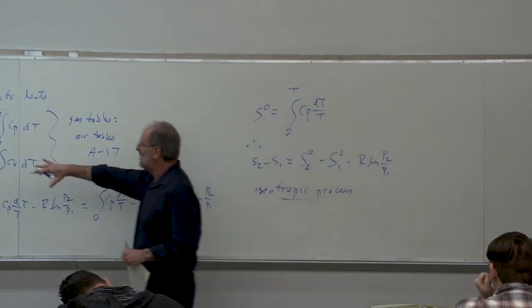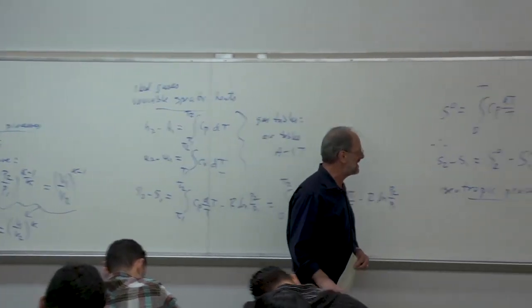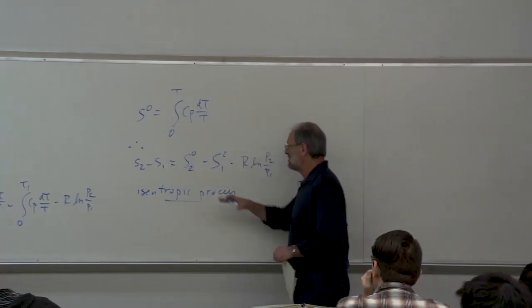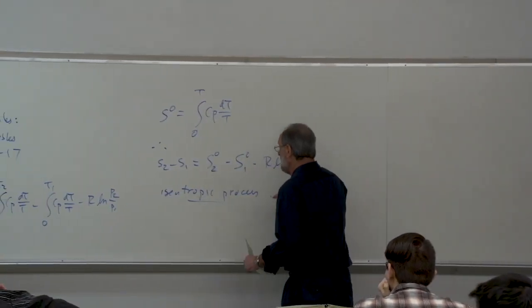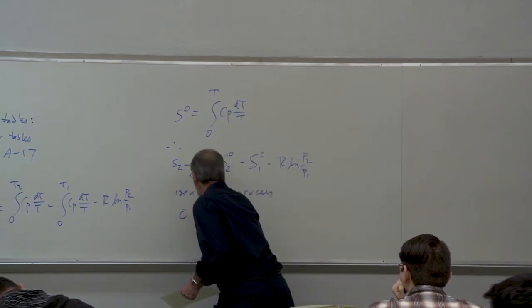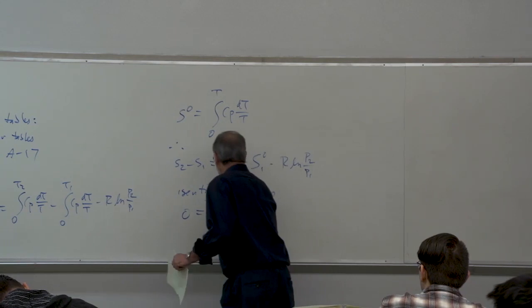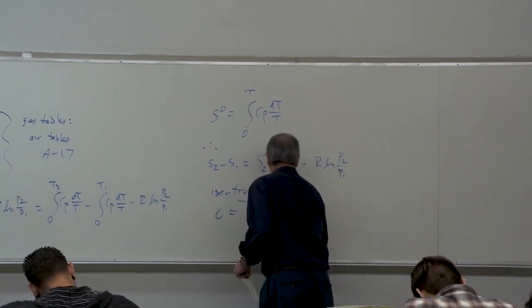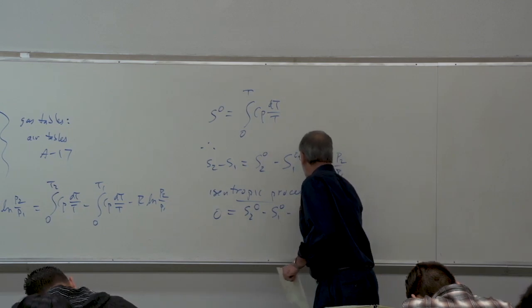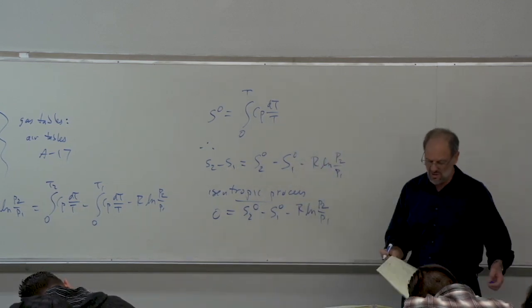So we already looked at that over here for constant specific heats. These are the equations that were developed. But now we need to use variable specific heat, so we're going to use the equations that are shown here above. So basically it's isentropic, so there's no entropy change. The left side of the equation is just 0. And then the entropy function at 2 minus that at 1 minus R log of the pressure ratio.